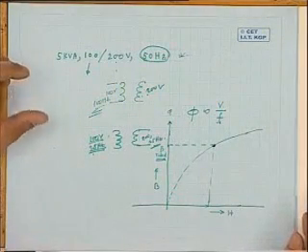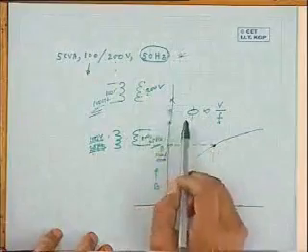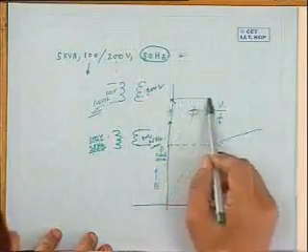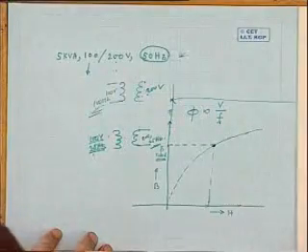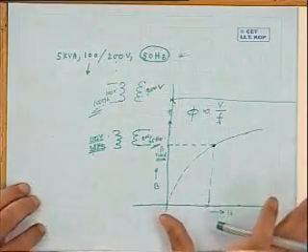Now the moment you apply 100 volt 25 hertz to the primary of the transformer, because the KVL equation is to be satisfied in the primary, the flux level has to be twice. But how much current will be needed to establish that flux inside the core of the machine? How shall I find out? This 2 times of this into this. And how much current will it take? You now draw a line here, and this one you extend. Wherever it cuts, that will decide the current. And what I am trying to tell is that the current may exceed your rated current of the transformer many times.